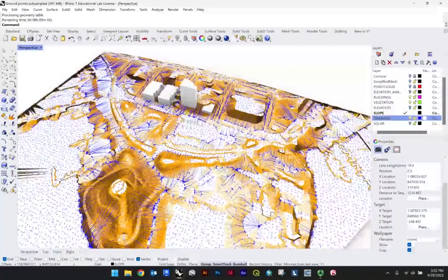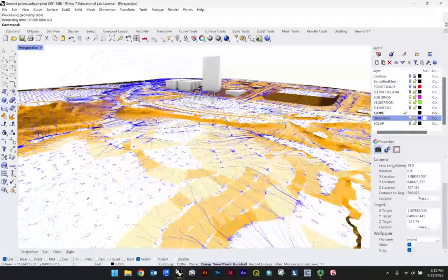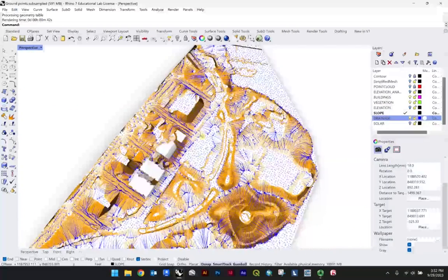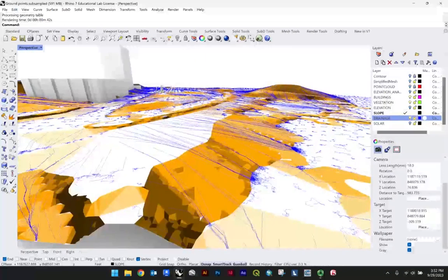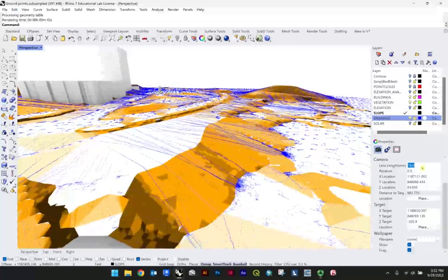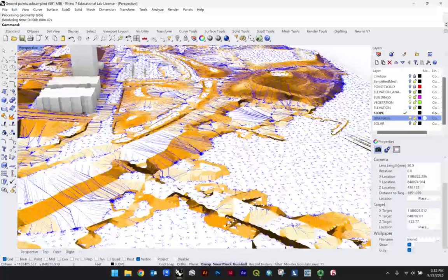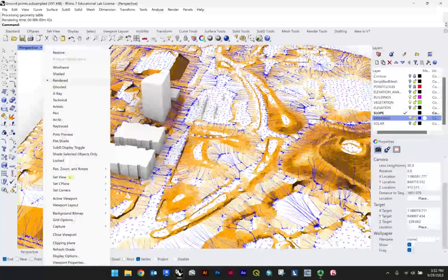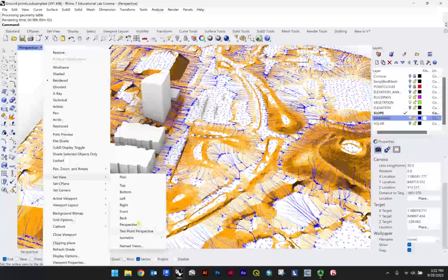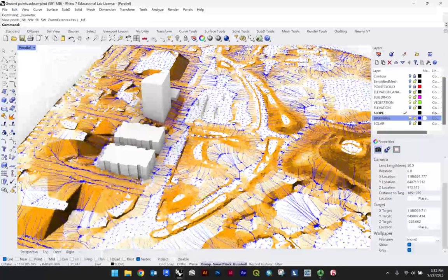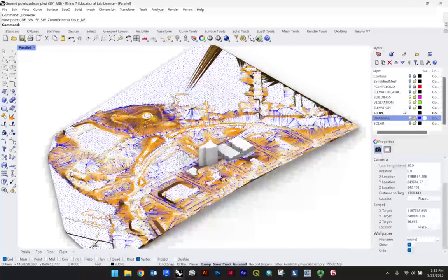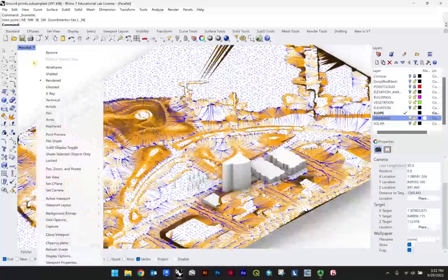If you find this view, just a reminder that we changed the camera lens length over in the properties, so this becomes pretty tough to draft like this. So just remember to switch this back to 50. That's the more traditional drafting lens length, at least if you're in perspective, versus your other projections, like your isometric projections, these sorts of views.